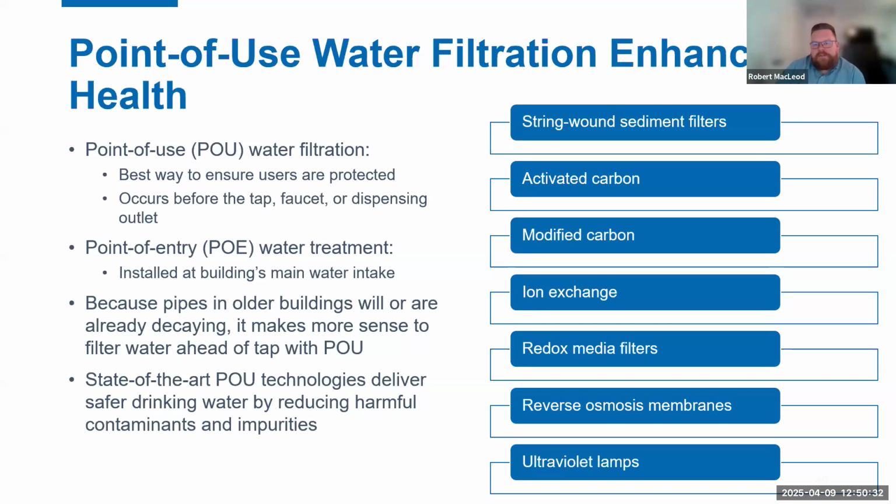And one quick note here: if the facility is using reclaimed water for any other system, it cannot be used with bottle fillers and water coolers. Reclaimed water can only be used for something like flushing toilets or urinal valves. Reclaimed water can never be used for human consumption. Even the filters are not going to necessarily be able to get those contaminants down to a safe point.